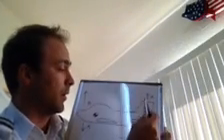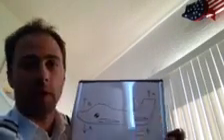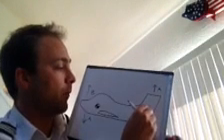And so what does that mean about our nose up attitude? Like we said, the tail down force is noticed right here. So now we've decreased our tail down force and we've decreased the nose up force. So now forces A and B are acting in the same amount.